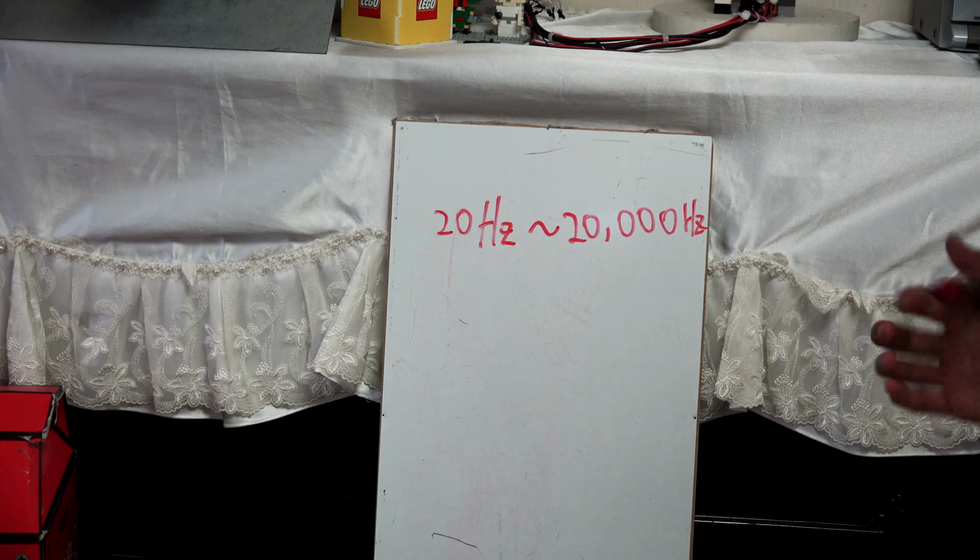So I put duration with pulseIn, echo pin for HIGH, so it will return the duration of how long it stays high. So I get the duration with the unsigned long, so it can hold a really big number.